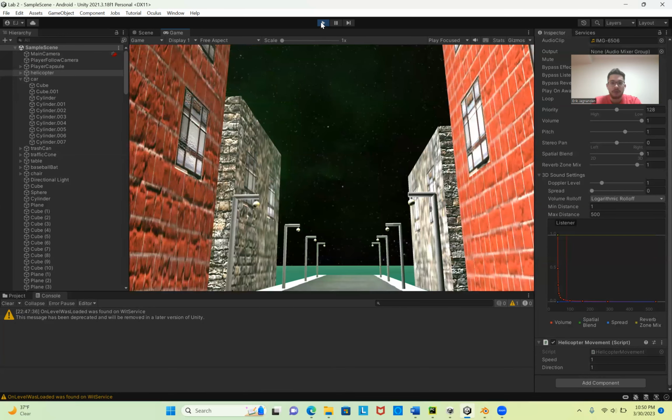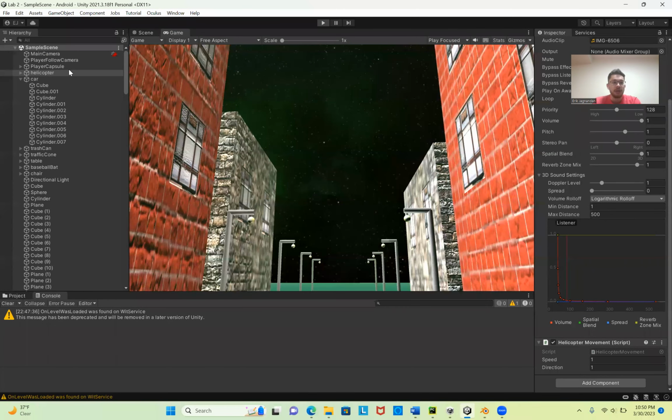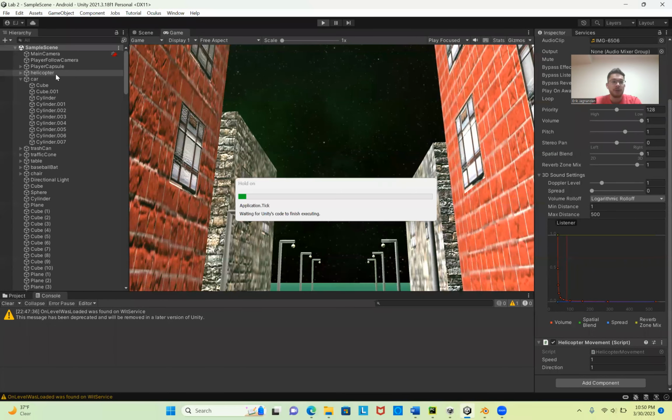And exiting first-person control now, you can see that this was done by applying an audio source component to the helicopter and the car, the 2 objects with 3D audio. And on that audio source component, the spatial blend aspect was set all the way to 3D, making the audio 3D in the sense that as the object moves further away, its sound level dissipates and gets lower and lower. So this was done not only for the helicopter, but also for the car. So you can check on that in a moment once Unity is done loading.